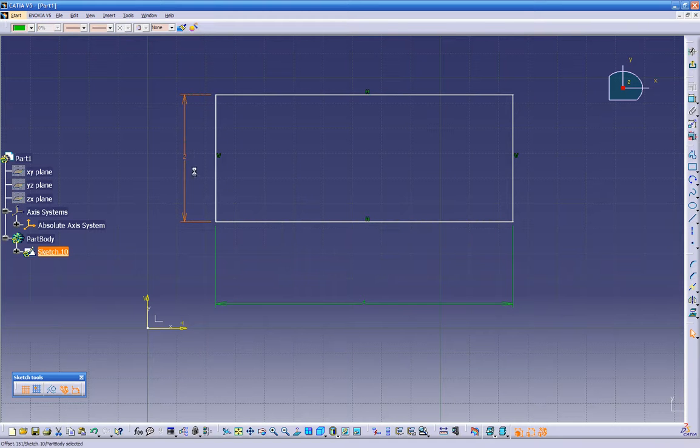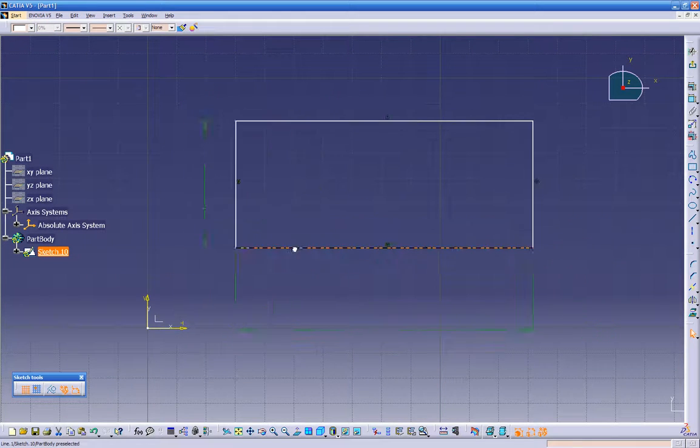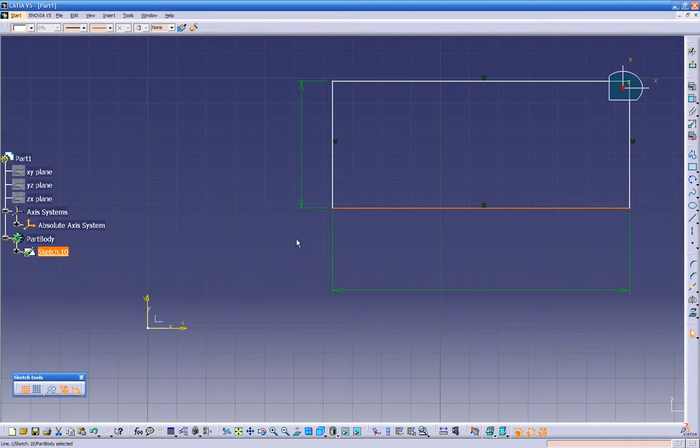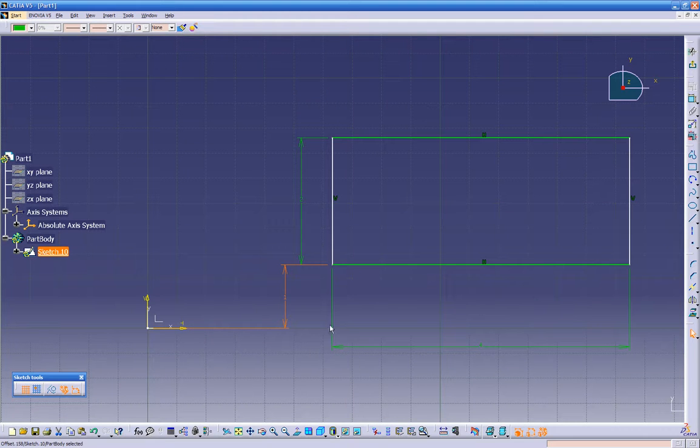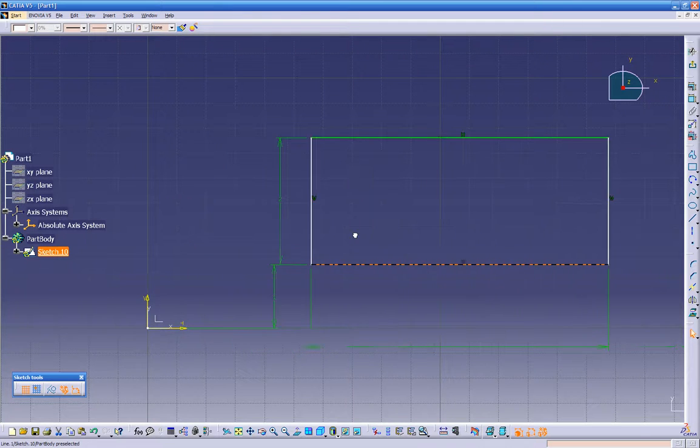It's fully constrained. The only thing not constrained is the axis of the sketch, which is important. So let's give it a quick dimension. See, it automatically knows it's fully dimensioned, and the moment I want to do this constraint, it knows I already have it somewhere before. But if I click on the horizontal line, then it'll let me put the dimension. So you can click OK, double click on the dimension, let's make this 1 inch, and see, this way I'm able to move the rectangle this way.